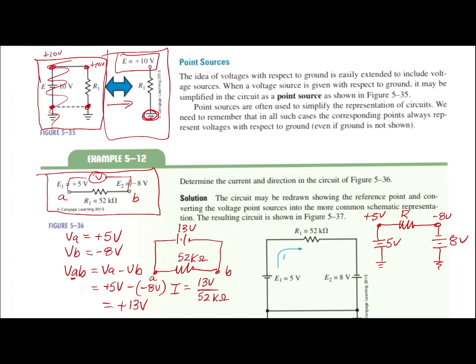And if we want to show that as a closed loop, we know we can connect grounds together directly because they're the same point. And now we have a closed loop, and what we have to do is look at our total motivating force. If we look at our total motivating force in this circuit and move our way around and account for all voltage sources, we can clearly see that these are series aiding connections for those sources, giving us an E total value of 13 volts.